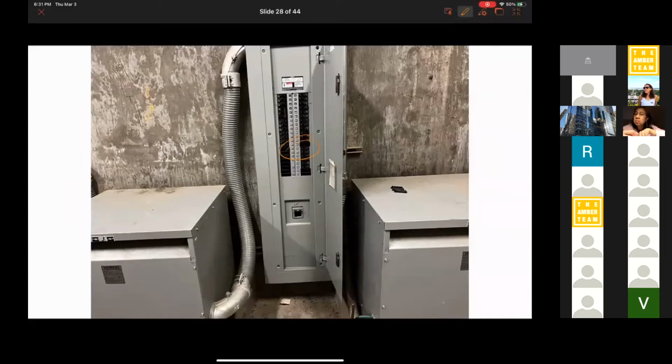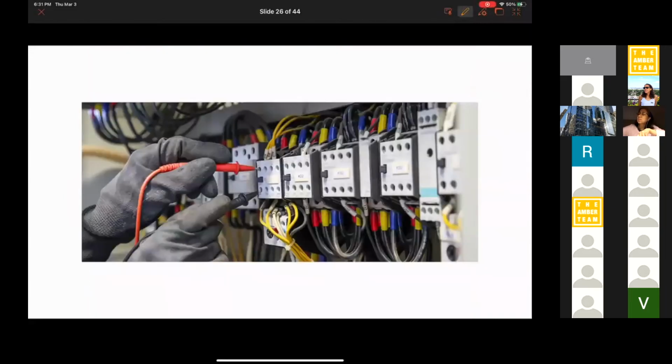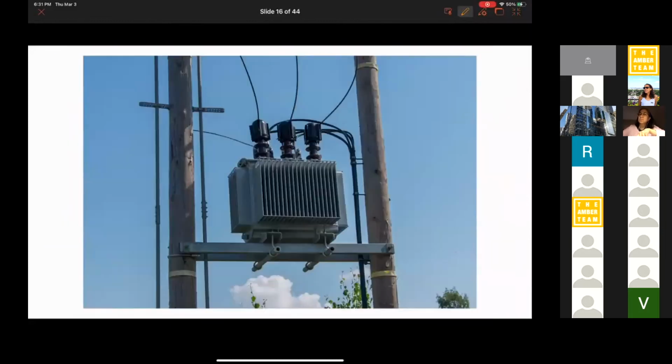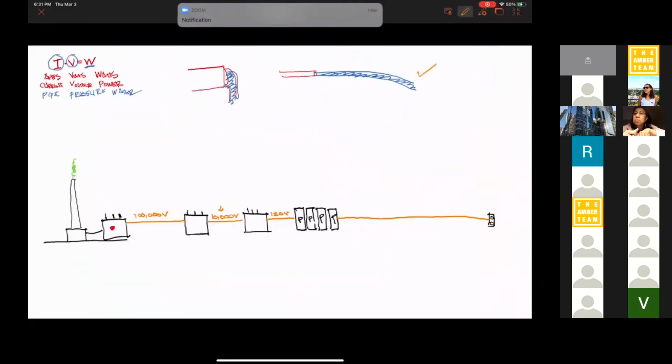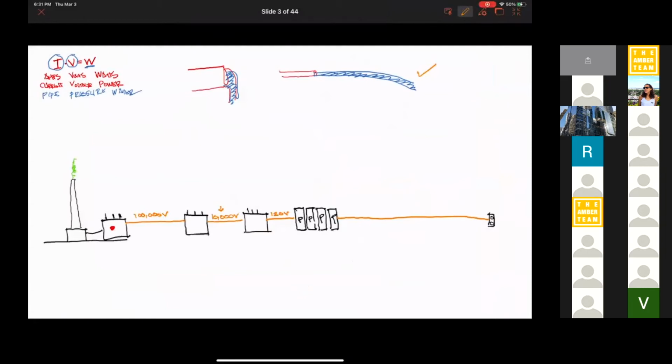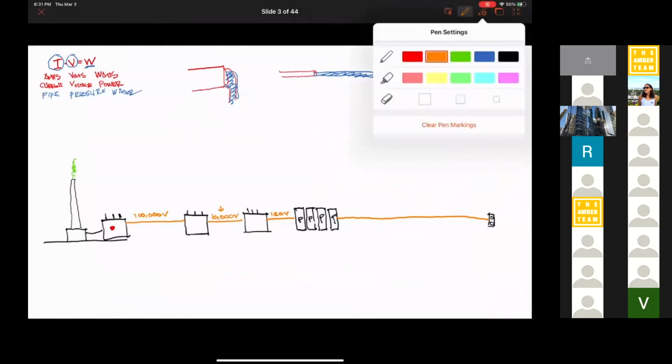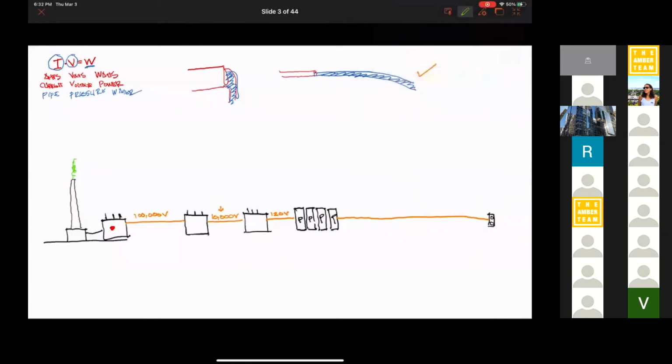Before we get to that, let's continue our diagram. We have 120 volts coming here, and the power is coming in. The orange is what's called the hot line, and we'll make the green line our neutral. Now, the neutral is grounded, but it is not the ground wire. That's a third wire, which is super confusing to people, and the topic of another 40 minutes of conversation.